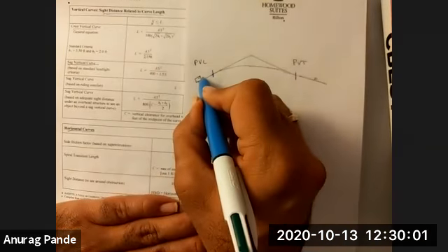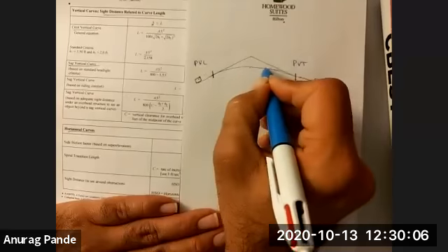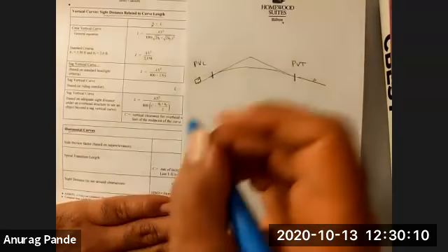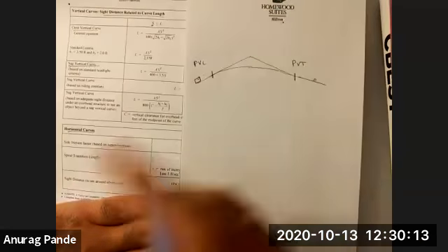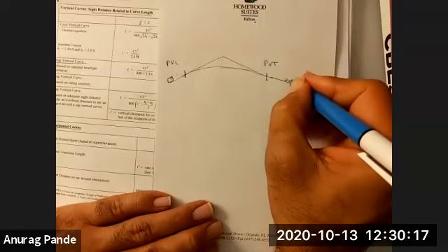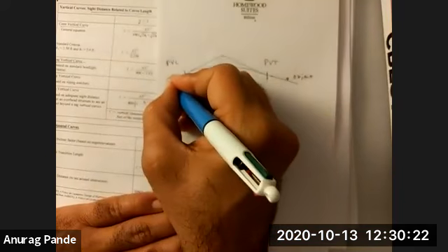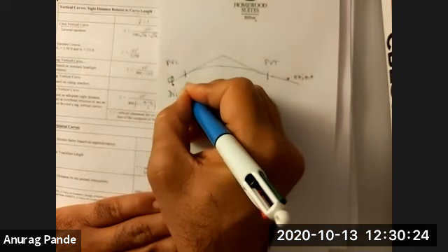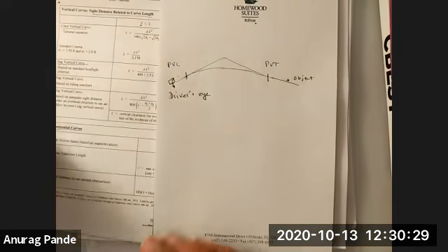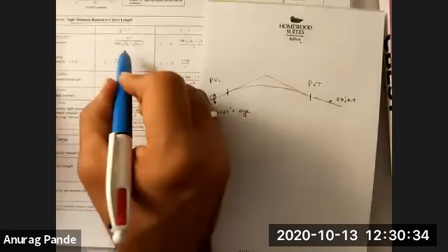Clearly, as you move forward, you will be able to see beyond the curve. So the critical dimension of the object height, around the bend, is based on the object that you need to see, and this is where the driver's eye is located. All those terms appear in the formula as the H1 value and the H2 value.